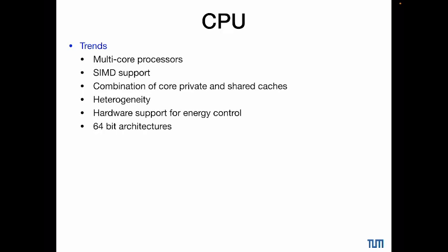And so it's important to optimize energy consumption, reduce it, and that can be done by adapting the processor dynamically to the needs of the application. So, for example, we can switch off parts of the processor that we don't need. If you have a processor and you run a single application with just one thread, and you have 8 cores, you don't need the 7 other cores, right? You can switch them off.